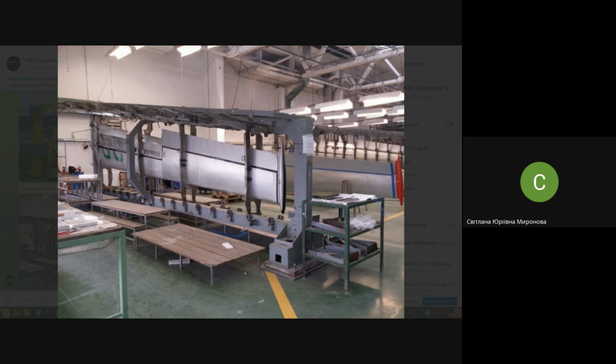Objects of junctions are different in shape, like left and right side, for instance. But whatever shape is different, the places, surfaces, holes, axes of holes must be common, must coincide. They should be coordinated beforehand. What we are going to talk about is jig mounting and coordination: how to provide this coincidence of assembled pieces of aircraft, aggregates, units, due to coordinating of jigs. I hope you understand the general idea.